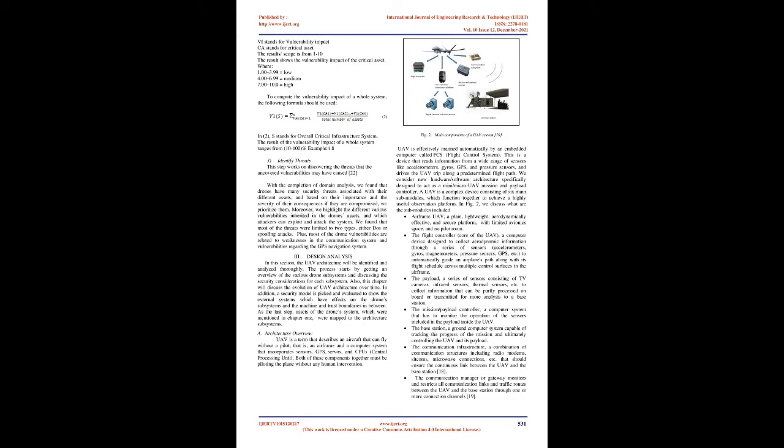Moreover, we highlight the various vulnerabilities inherent in the drone's assets, which attackers can exploit to attack the system. We found that most of the threats were limited to two types, either DoS or spoofing attacks. Plus, most of the drone vulnerabilities are related to weaknesses in the communication system and vulnerabilities regarding the GPS navigation system. 3. Design analysis. In this section, the UAV architecture will be identified and analyzed thoroughly.